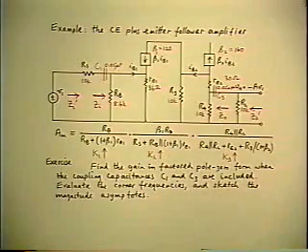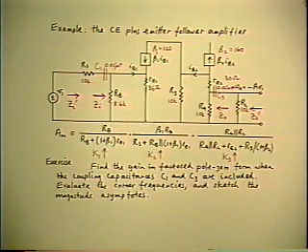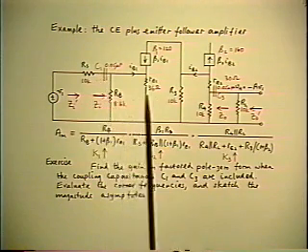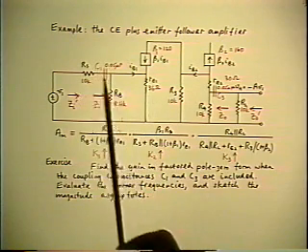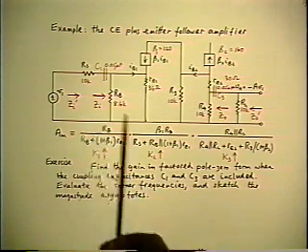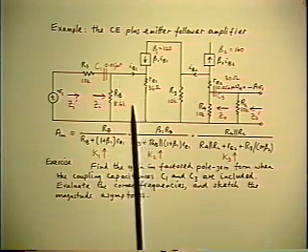But notice that wouldn't work if we wanted to put the coupling capacitor and the bypass capacitor in at the same time, because they do interact, which means that once you put one of them in, the driving point impedances seen by the other one will become reactive, depending on the first element, which means you won't get the nice, convenient, immediate pole and zero result. You'll have to do a bit more algebra. That's where the two extra element theorem comes in handy. Well, again, we're not going to do that case here.